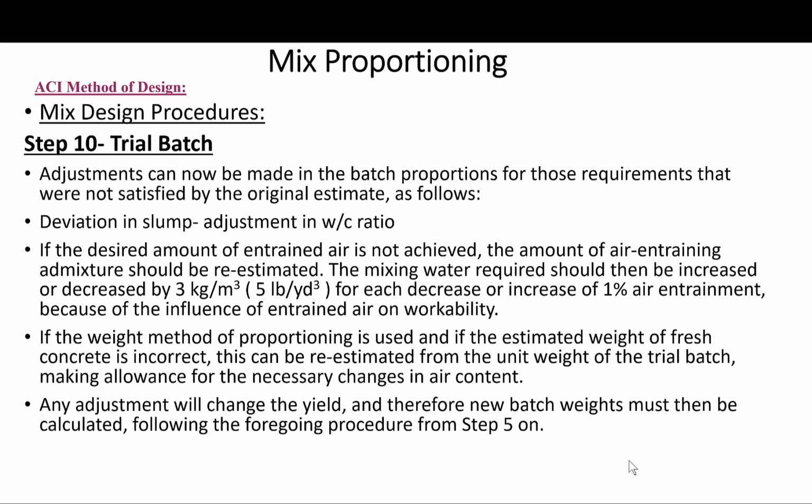Okay. If the correct slump is obtained at a lower water content, it is permissible to reduce the cement content to reach the design water cement ratio. Okay, consistent with any specified limitations on the cement content. And again, as I said, we could lower it, but if there is a minimum, you cannot go beyond that. If the water content must be increased to obtain the desired slump, then the water cement ratio will be increased. In this case, additional cement must be added until the design water cement ratio is again achieved. Okay, or you have to redesign the entire mix.